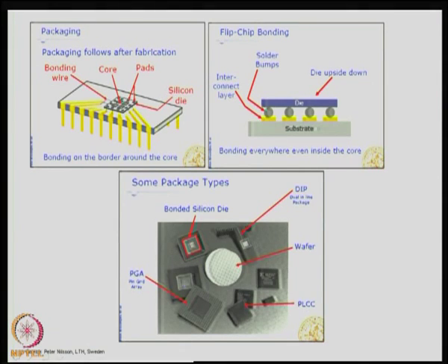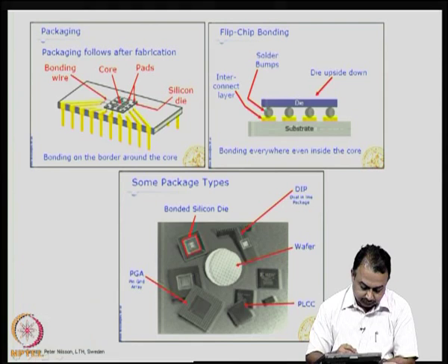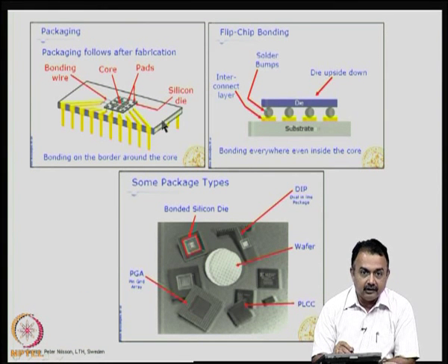If you look at the slides here briefly, you can see on the left we have here a substrate. Here we have the substrate, the lead frame which houses the die that you have manufactured, and here you can see on the die in the periphery various die bond pads that are marked in black.